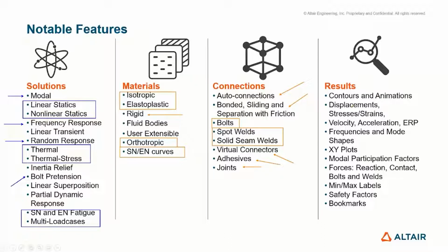Now, last but not least, in terms of the results, like we said, if you're conducting, let's say, a modal analysis in this aspect, what you will find is that you always get the same set of results from it. So you always get your frequencies and mode shapes, and you always get the modal participation factors from it. Say if I wanted to look at a linear static analysis, from there I'll always get my displacements and strains and stresses,